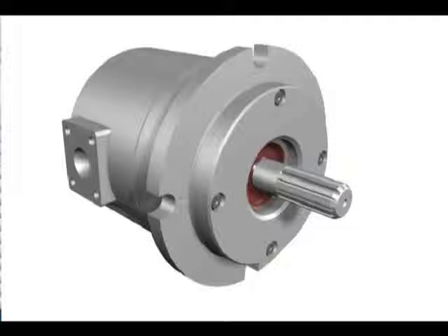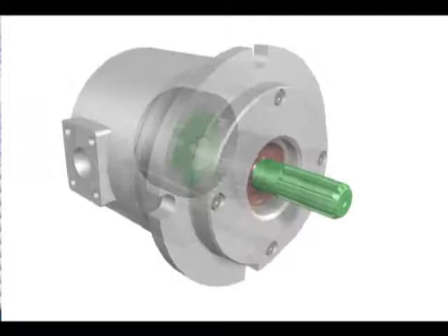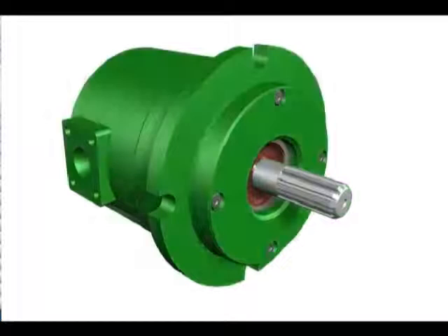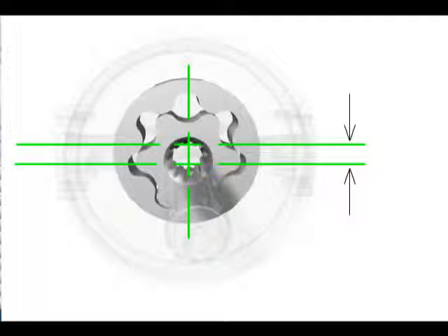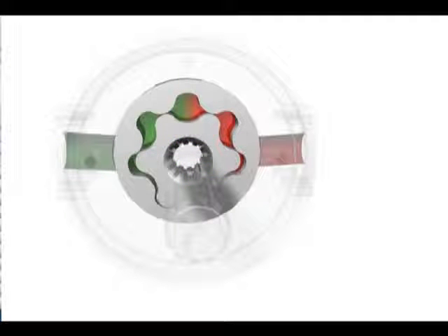A gerotor pump is an internal gear design. The main components of the gerotor pump include the outer gerotor element, which is an internal gear, the rotor or internal gerotor element, which is an external gear, the input shaft, and the housing with the ports. The rotor, which has one less tooth than the outer gerotor element, sits offset in the outer element. This creates an opening cavity between the two gears. The two opposing teeth divide this cavity, creating a positive seal between the inlet and the outlet.